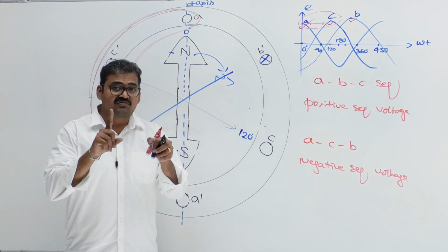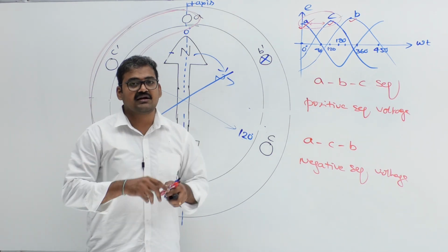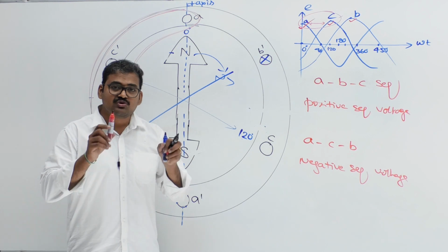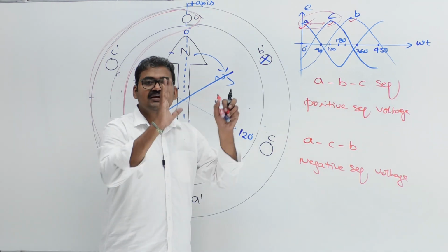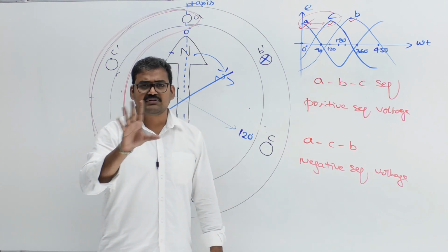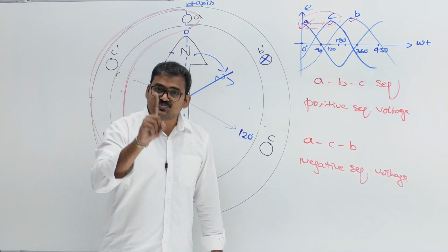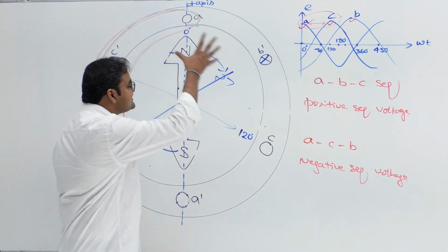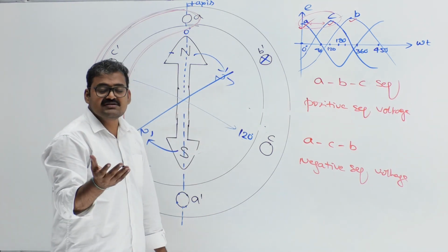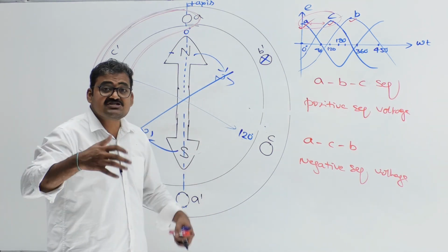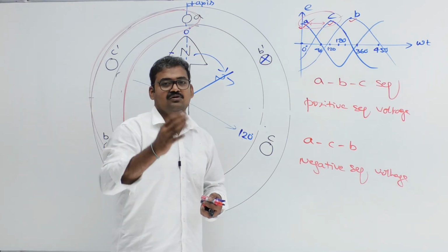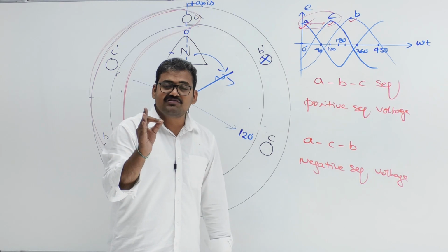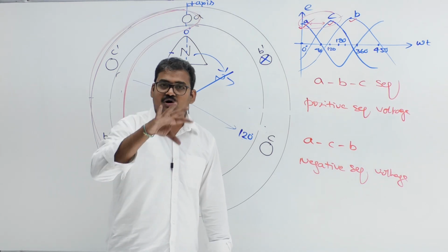Okay. So there is always a confusion between mechanical angle and electrical angle. What students generally feel is space angle means mechanical, time angle is electrical. That is absolutely wrong. Space angle is nothing but a physical angle. Time angle is generally not a physical angle, it's a virtual angle we use for voltages, currents and all. Space angle we use for windings, slots, coils and everything.